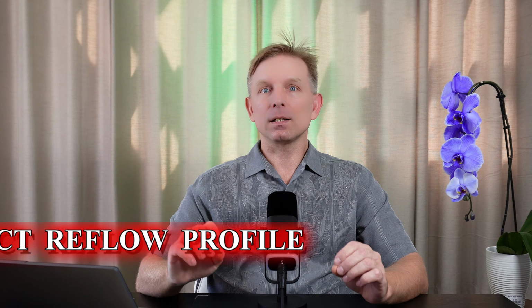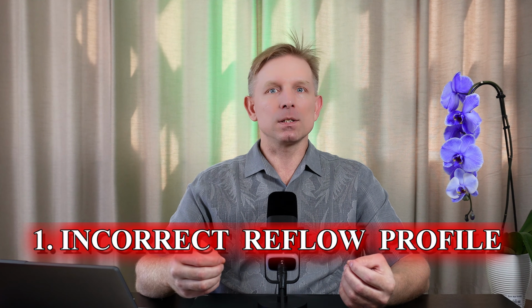First cause: incorrect reflow profile, creating temperature differences on the two pads. In a reflow oven, different profiles are used for leaded and lead-free solder pastes. In one of my upcoming videos, I will show you how to create profiles for the oven. In the first case, the conveyor speed is too high. The PCBs do not spend enough time in the oven's second zone to stabilize their temperature. You need to align the profile with the solder paste manufacturer's recommendations, then test the actual temperatures in the oven zones using a thermal profiler. It's very important. The correct profile will preheat the PCB and components evenly by the time the solder paste melts.